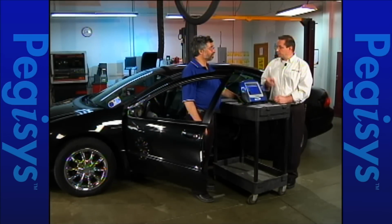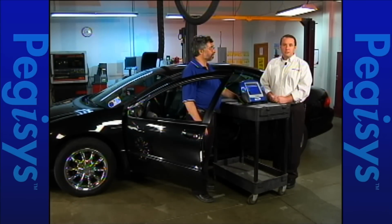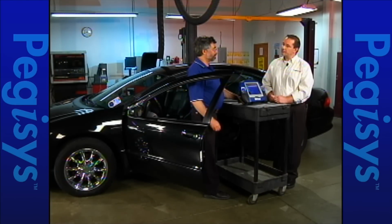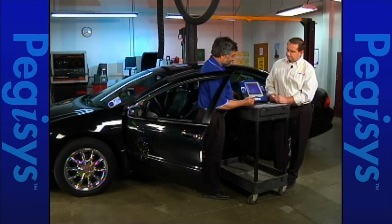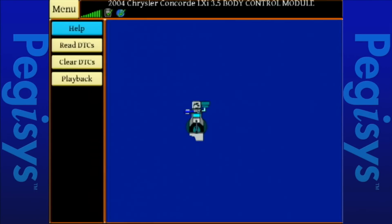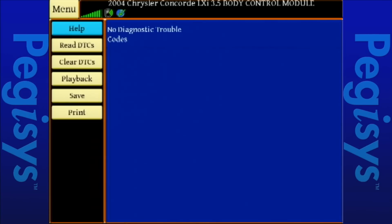Incidentally, on this system, the climate control is being controlled by the body control module. So I think what we're going to do today using the Pegisys is go ahead and check for diagnostic trouble codes in the body control module. Steve, my assistant here, is going to do that. We're going to access diagnostic trouble codes in the body control module. And it looks like we have no diagnostic trouble codes in the body control module. So let's go ahead and back out.